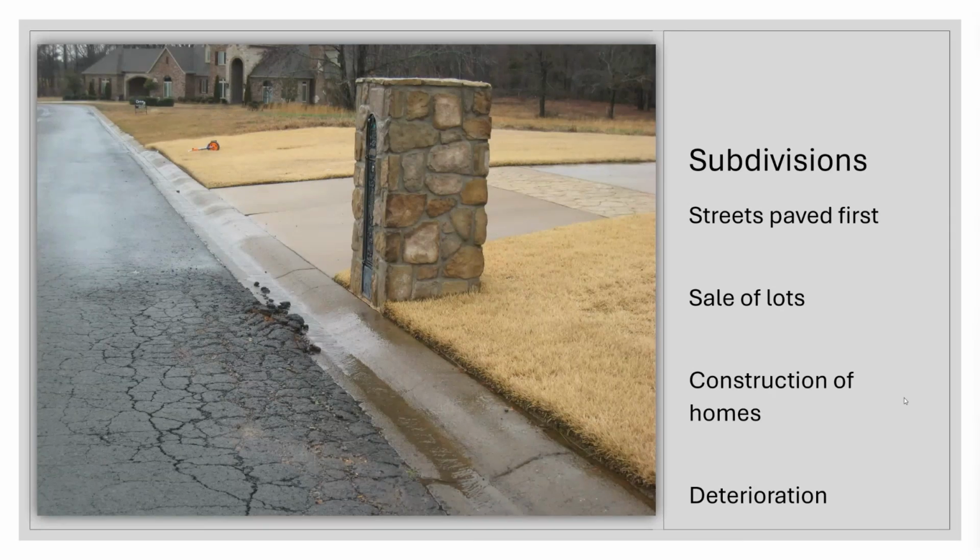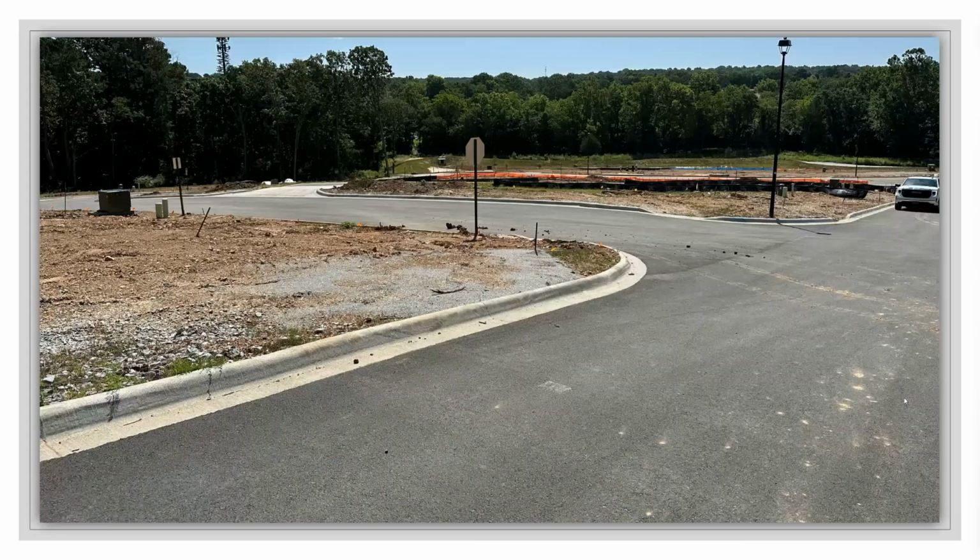Part of that, I think, comes from the fact that when someone builds a subdivision, the developer will come in and put really nice streets. They put in their curb and gutter because they want to sell the lots. They want it to look great. But that is the worst time to build your roadway, because the first thing that has to happen in there is that we bring in all of the construction equipment and trucks that are hauling: concrete trucks, brick trucks, all the supplies are coming in. And those are the heaviest loads that those pavements are probably ever going to see, all at the beginning.